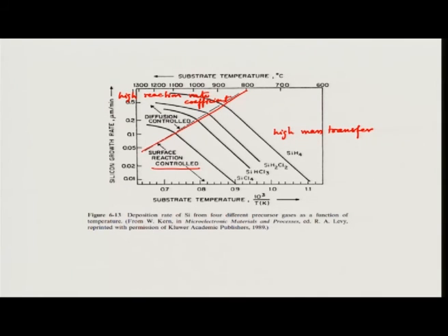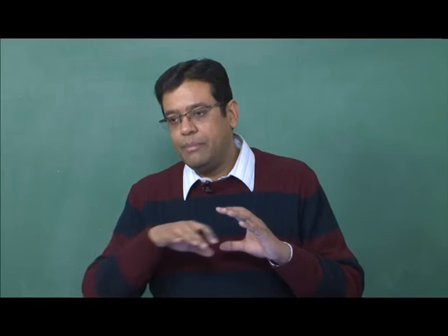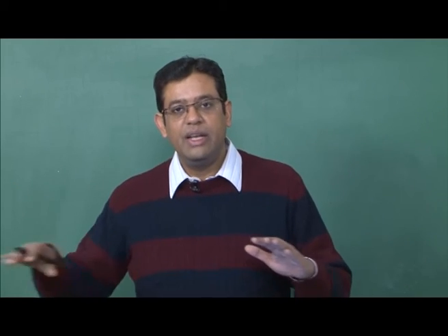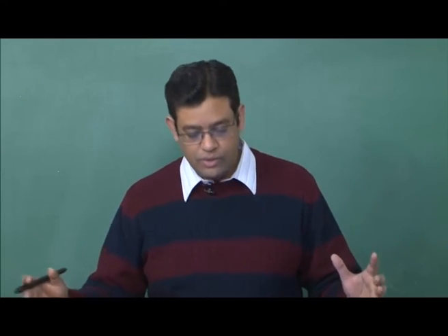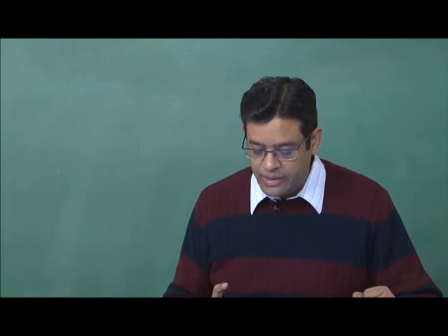Now, what is important? That we want to have uniform deposition. For uniform deposition, my mass transfer should be high and reaction rate should be slow, so that my concentration is distributed very evenly across the large area or all the wafers. So, that is one thing.